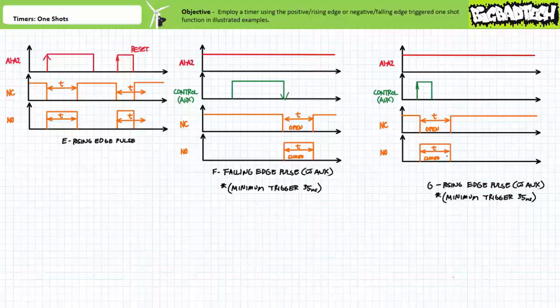Finally, to set this particular multifunction timer to perform the pulse forming function with auxiliary voltage for a period of 5 seconds, a technician would rotate the function selector to function G. Then a technician would choose an appropriate delay of 5 seconds using the previous steps.